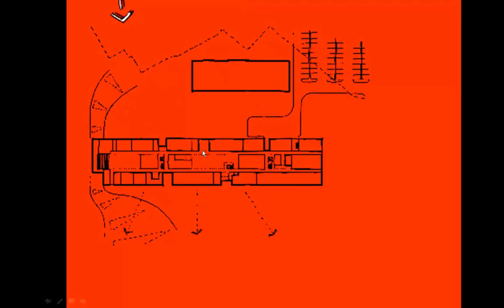And the important thing environmentally, which we touched upon this morning, is that in the UK and in the northern temperate zones, your south facade, ideally, your main facade is orientated south. Okay, so it's facing south. Or if you can't, try to get it within 30 degrees of south.